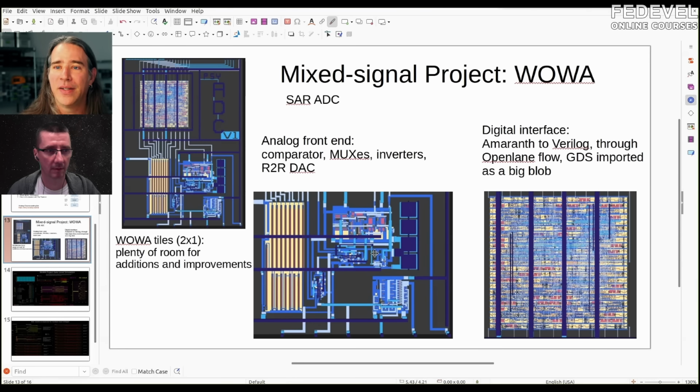And then I added stuff around it to be able to calibrate it, to be able to turn it on and off. These four squares are one tiny capacitor. Capacitance, resistor, you get tons of MOSFETs in here, easy. You get resistors, pretty easy. Capacitors you can get, but they are tiny. There's a project where a quarter of the space in the next tape out is taken up by a capacitor, and it's 0.5 picofarads. I was worried about a couple of picofarads on the traces of my PCBs, and this is less than that.